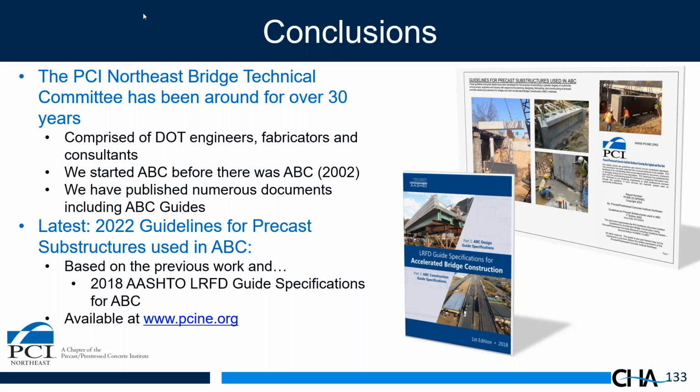But that's why we developed a lot of details with cast in place footings, because footings are probably the most difficult thing to move and ship, especially long distances. So we wanted to give options, and if shipping a heavy precast footing in your region is difficult and expensive, we gave you an option with cast in place to make it work without that heavy footing.